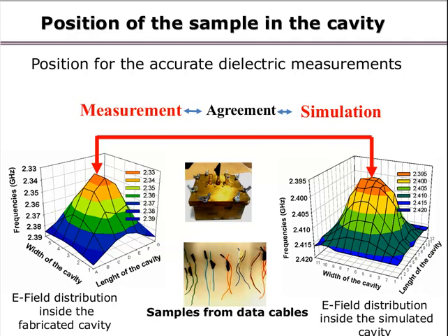The dielectric samples were obtained from the lower categories of cables such as Category 5 UTP, Category 6 UTP, Category 6 FUTP, and they were also obtained from higher categories of cables such as Category 6A FUTP, Category 6A FFTP, and Category 7 SFTP cables respectively. We tested all the dielectric samples at room temperature first to obtain the baseline dielectric constants across the 3 frequencies.